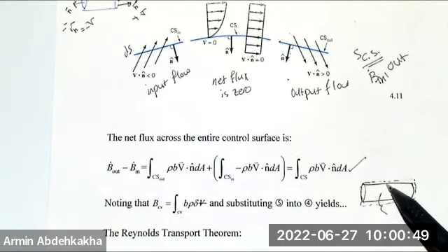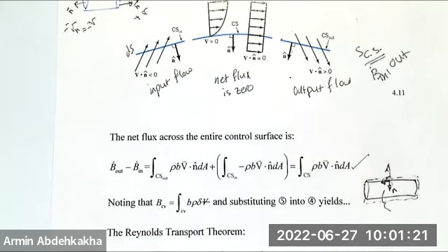But you know that the velocity here, not only because of the no-slip boundary condition is zero, but it's always parallel to the surface, right? It's not passing over the wall. It's not possible to pass. And also by mathematics, the velocity is parallel to the surface, and the normal direction is always this way, or it's outward. It doesn't matter, because the angle between these two is 90 degrees, and the cosine of that is going to be zero.